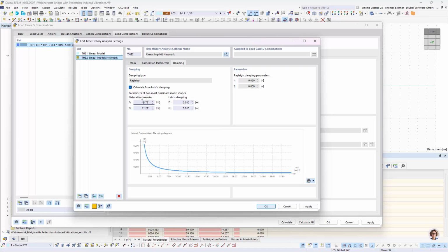And one hint for at least non-linear time history convergence: if you had contact with that analysis already and you didn't get your analysis to converge, just try setting this beta value to 0. Because with that, I don't know what is in the model, right?